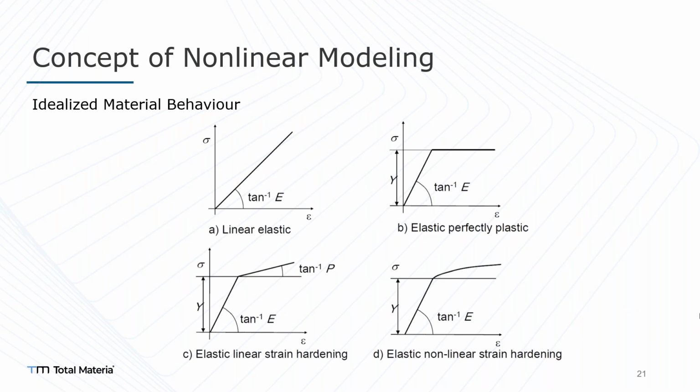So for nonlinear strain hardening, what you can use, which is well known, is Voce material models or Johnson-Cook plasticity models, which are really well known and very popular. It has a really big database. But those values are not actually the same for all materials. Different sources give you different Johnson-Cook models and so much information, which makes it very hard to find which one is the accurate one.